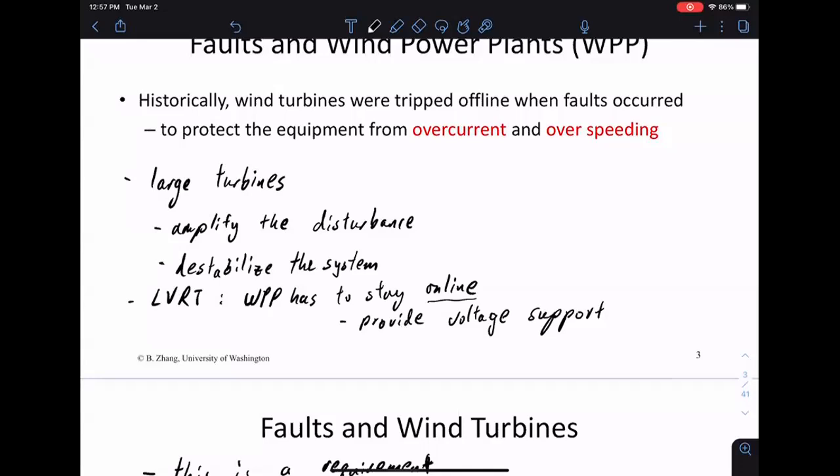Any guesses, right? What's a reasonable number that you think a turbine can stay online for? Is a second reasonable? Think back to the calculation we did, right? When we're calculating basically the resistance, how much power you have to dump through a resistor when a fault happens. Same idea, how long you have to do this? Can you stay online for a second?